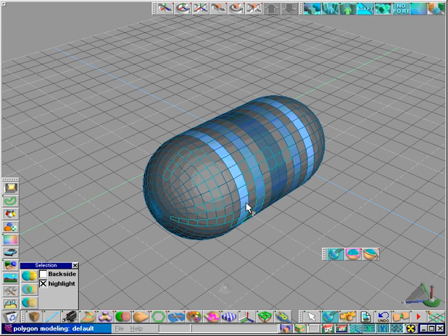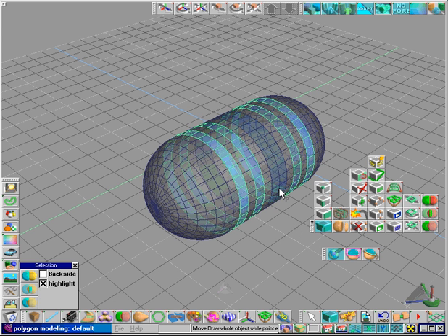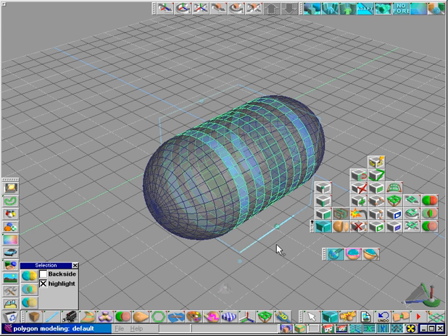By holding down the Control key and selecting a face, we can select all the faces that have the same material. In Point Edit mode, sequential clicks on different materials while holding the Control key will create material group selections. Not only can we change the selected materials to something else all at once, we can perform geometry manipulations on the faces like so.